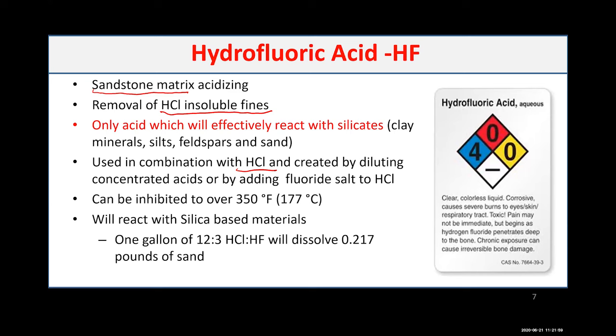One of the other concerns, as you can see from the SDS diamond, is the characteristic of HF: it has a health rating of 4. This is one of the nasty chemicals that you will have on location. You don't want to breathe it or touch it or anything. So from a health point of view, that's not a good chemical to be around.